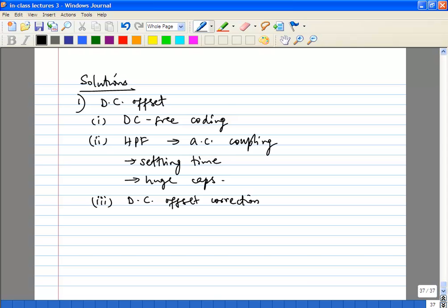Okay, you can do it periodically. There are many techniques. That's why it's calibration. So it will be part of the calibration, because typically your DC offset will be constant. It won't vary with time. At least the component from your circuit due to mismatches will not vary with time. So you can use calibration. You can use analog techniques also, definitely.